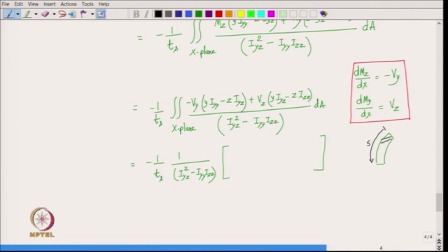and then this is the shaded area, that is the x plane here, and we have integral y dA. So, that is the y centroid of this shaded cross section times the area. For example, when we have integral y dA, let us denote it by q of y, and integral z dA, let us denote that by q of z, but only for the shaded area. Okay.